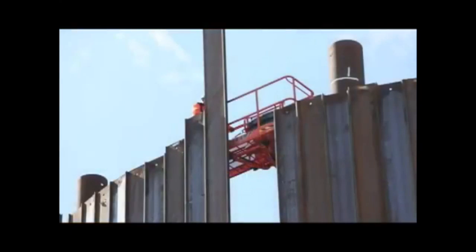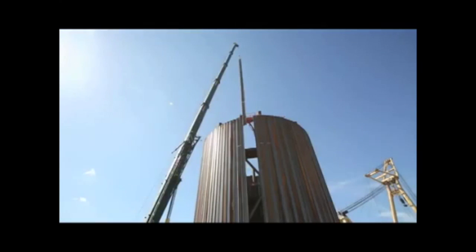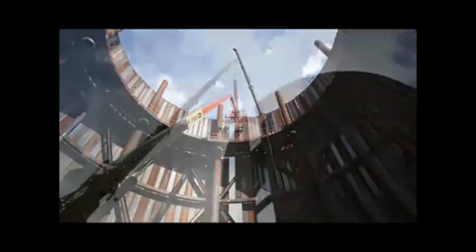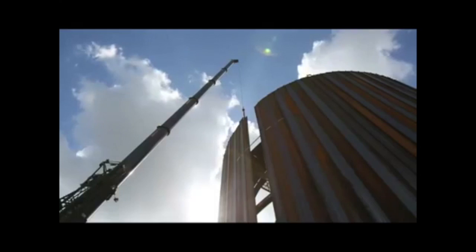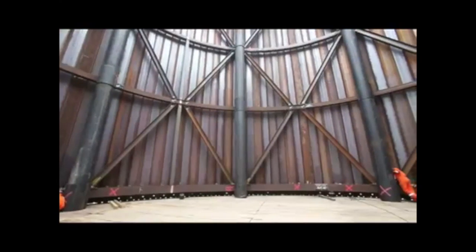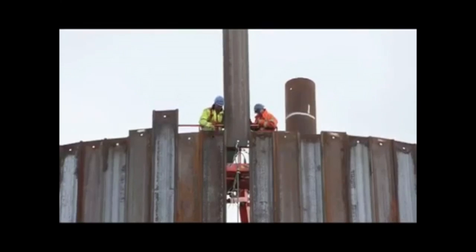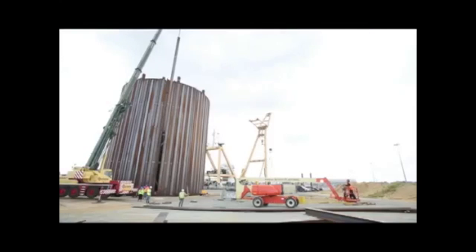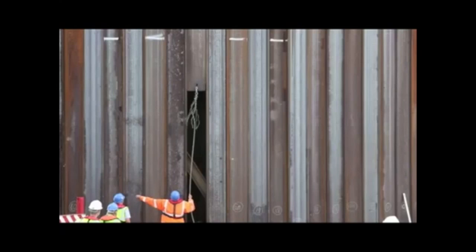Deep foundations are used wherever shallow foundations cannot be used. Typically, the reason that a shallow foundation can't be used is because the topsoil is expansive, or the soil underneath has a low bearing capacity, or we have a deep frost line. They may also be used in buildings that house delicate instruments that are sensitive to the settlement of shallow foundations.